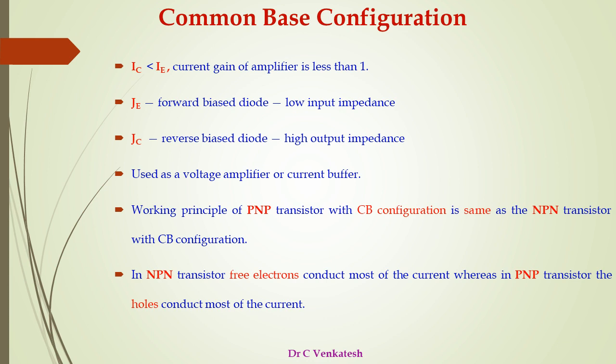Transistors with low input impedance and high output impedances provide a high voltage gain. Even though the voltage gain is high, the current gain is very low, and the overall power gain of the common base amplifier is low as compared to the other transistor amplifier configurations.